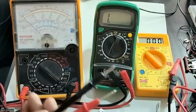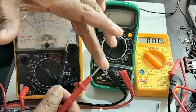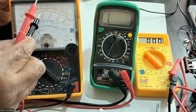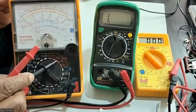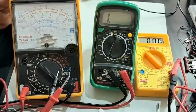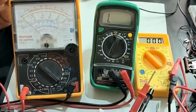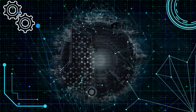And please remember, when it comes to DC, compulsorily you have to be very careful with the polarity. Black color is negative, red is positive. Same thing here also. The only thing is, wherever it goes, whatever reading you get, like if it comes to 4, then it will be 4 volts when it is kept on AC or DC voltage. Okay. So these are the 3 measuring equipments I'm talking about. You should know how to use them, and you have to use them very, very carefully. To this point, you should know very well.